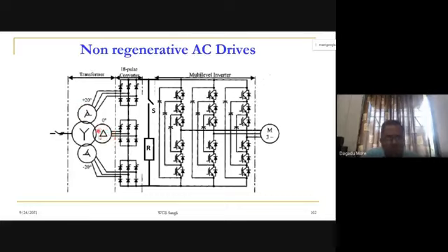Whereas with respect to these delta line voltages, in this extended delta, you see here there is a change in the connections, and here we'll get a minus 20 degrees phase shift. So the three line voltages have a phase shift of 20 degrees. Three line voltages means the three-phase voltages supplied to rectifier 1, rectifier 2, and rectifier 3, and they have a phase shift of 20 degrees with respect to each other in the line voltages. And so we again get the 18 pulse.